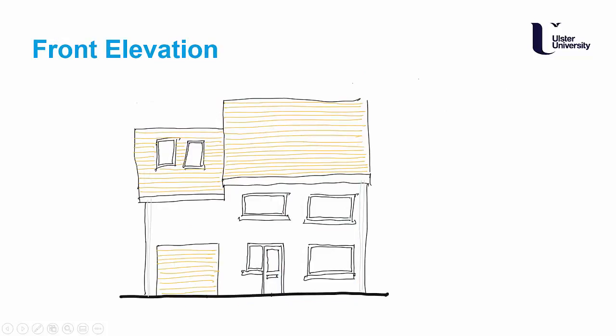Moving on to thinking about the elevations then, this is a front elevation view. Even at this stage we can start to think about where the materials are going to be and thinking about finishes, and down to the level of detail looking at roof lights there, and thinking about the position of the windows, the doors, and even the finishes. So here we have the roof finish sketched on, and we even have the down pipes indicated here with 2 grey lines.